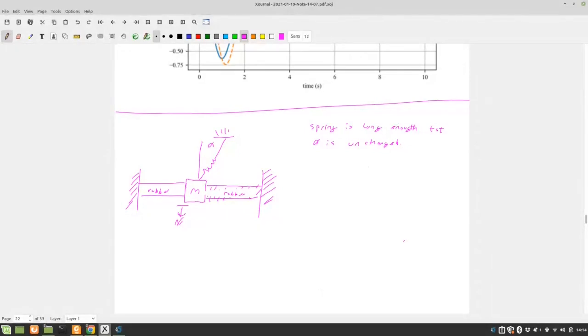So let's do that. Because we're acting in the vertical direction, we're probably going to want a mass that looks something like this. So this is our fixity. Our spring is at an angle, but what about our dampers? We assume that these add damping, but we only have 1 degree of freedom, so we can't really add a damper in this direction. That doesn't make sense. So we need to add a damper vertically, so let's go ahead and do that.